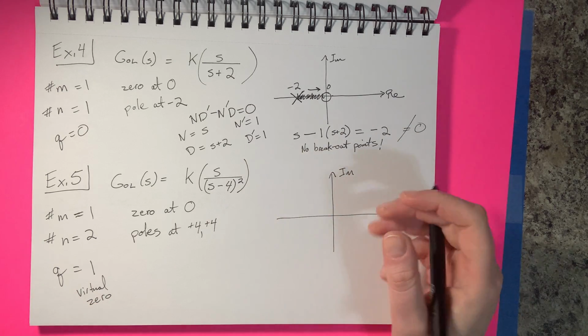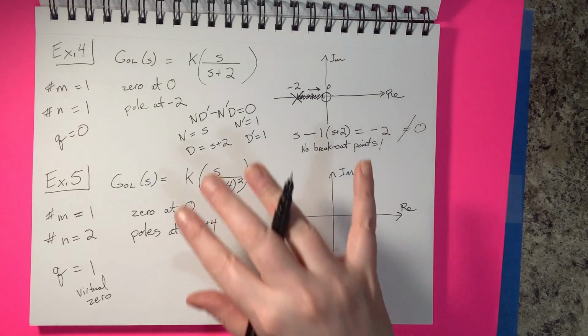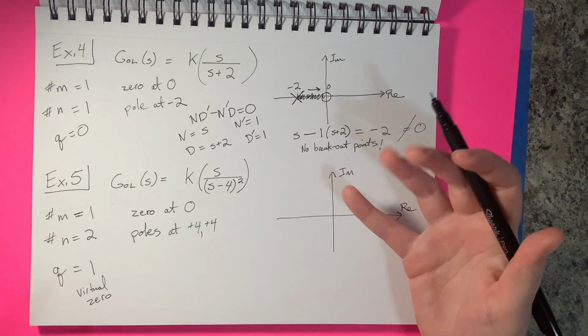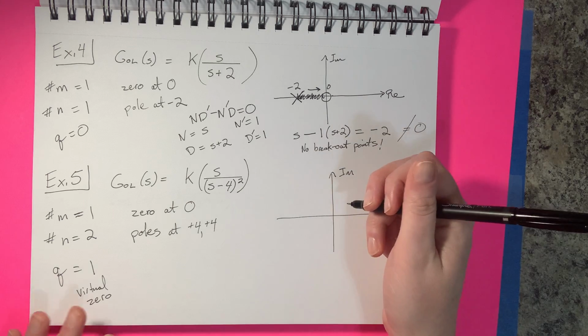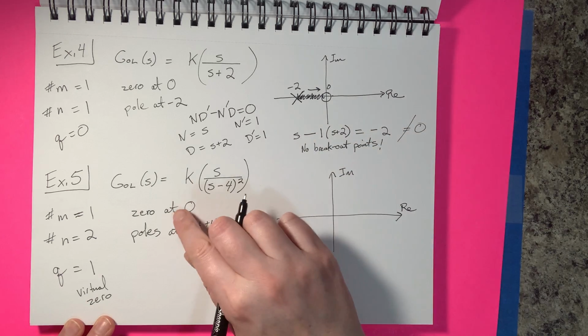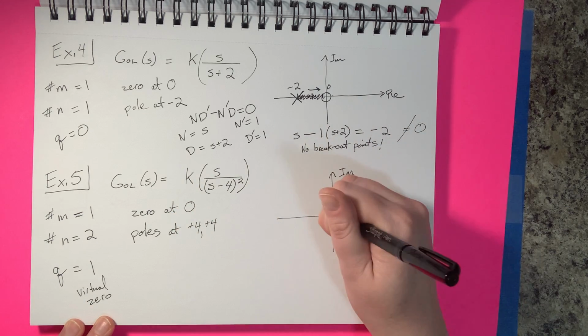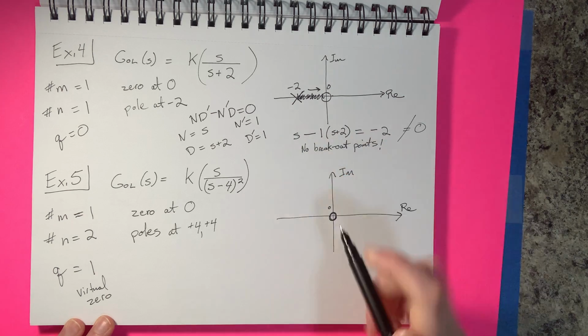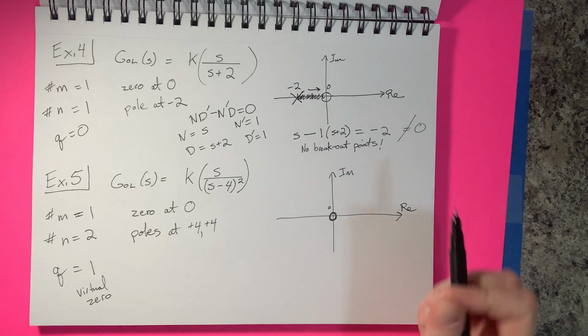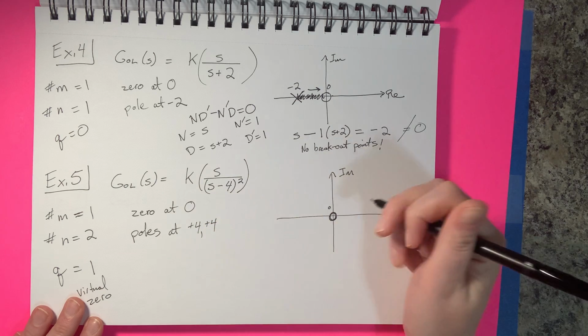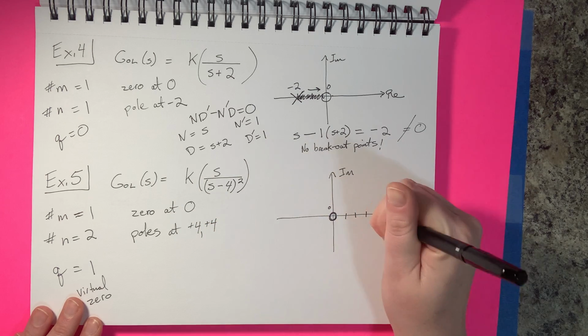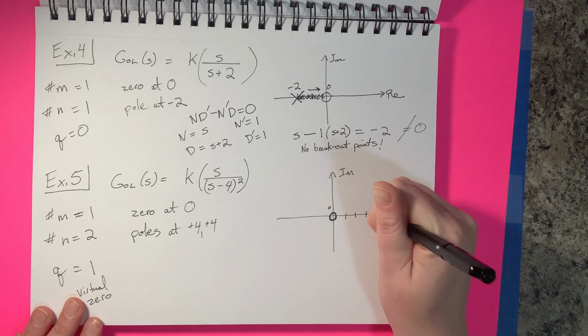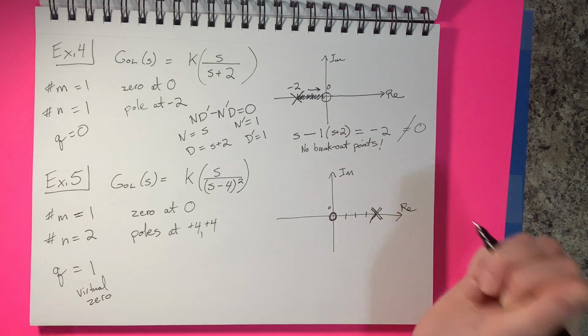It's a certain type of plot, so it's a root locus, not a root locus plot, but I often say that plot anyway, so oh well. Anyway, so we'll plot the 0 at 0, and then we have the poles at positive 4, so 1, 2, 3, 4 out here, and we have a double pole, so we have 2 of them.